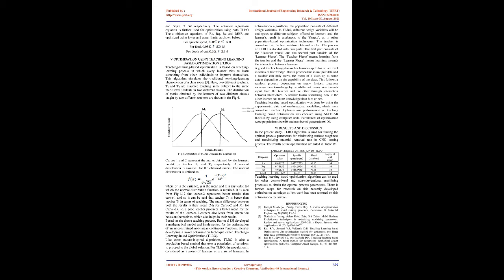Total number of experiments done is 20, and the workpieces of which are shown in Fig. 2. Material removal rate, MRR, measurement was done by measuring the weight before and after the machining is performed. MRR can be expressed either in mm3/min or in gm/min. Here gm/min is used for MRR calculation.